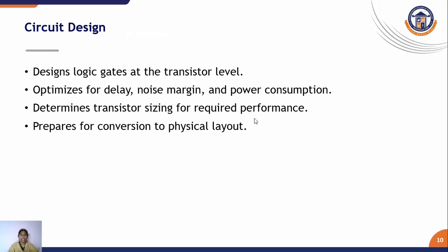Before that, we followed the logic gate level. Here we convert it into the transistor level. Once converted to the transistor level, we optimize for delay, noise margin, and power consumption. Here we determine transistor sizing for the required performance. We also prepare for conversion to the physical layer.